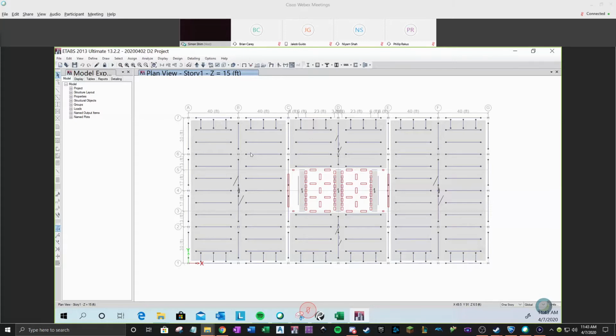Very likely we are using AutoCAD, like an architectural background, right? So DXF or DWG, we bring into ETABS as an architectural background and use all the reference lines and define the center point of the columns and walls, because usually architects don't draw the center line on their architectural drawing until they establish the grid system.